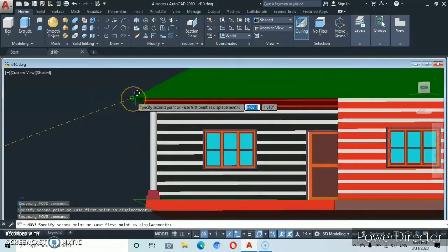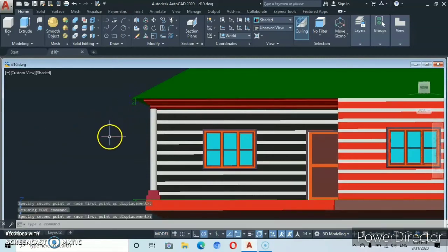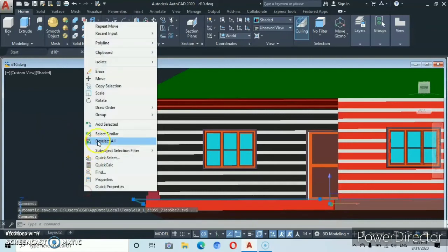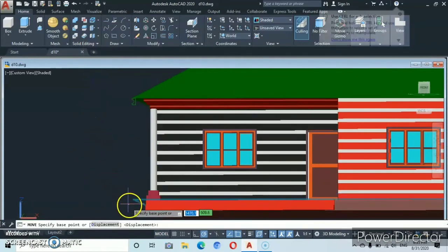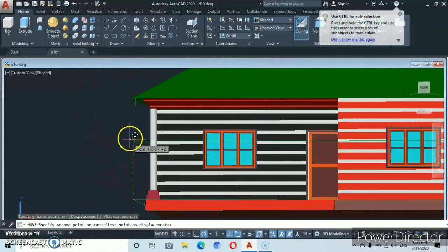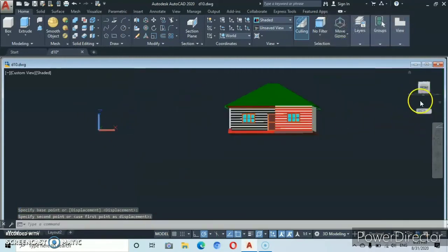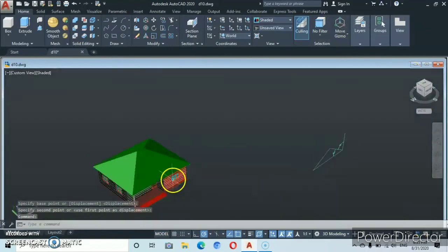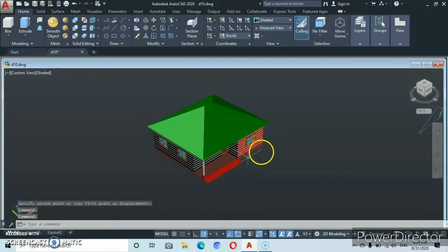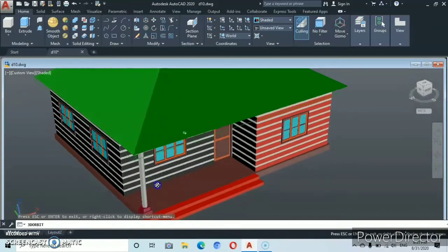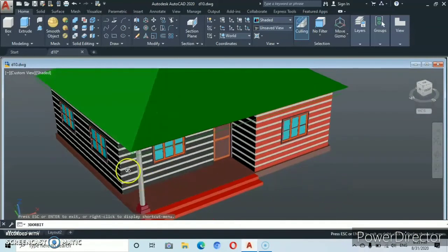Then you come here at this tip, then you click here. Now I would like us to take this polyline which we kept and move it up. So you click and move it up to this outer end as well. Very good. Let's go back to home so that everything will be visible. We try and orbit it a bit so that you can really see. Then we zoom.